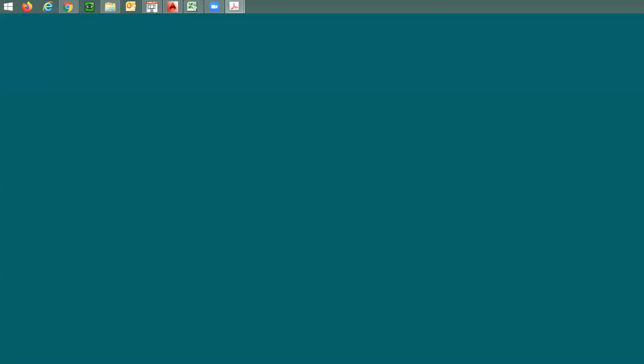This is why you need to have a spreadsheet. Are you done with your spreadsheet? You remember we talked about doing a spreadsheet? It is going to be very helpful now, because you can do a spreadsheet for the reinforcing. You put, for example, number 5 at 14 or number 5 at 16, or number 4 at 16 inch, number 4 at 14 inch, number 4 at 12. Every time you put the reinforcing there, you get phi M sub n as output. Then you compare it with your M sub u and see which reinforcing amount is good for you. And at the end, once you have your choice, you put your calculation together and send it to me.